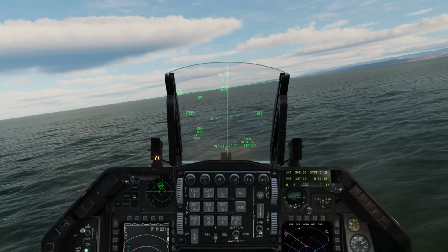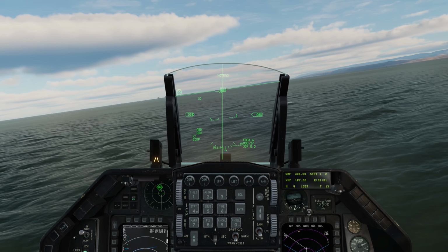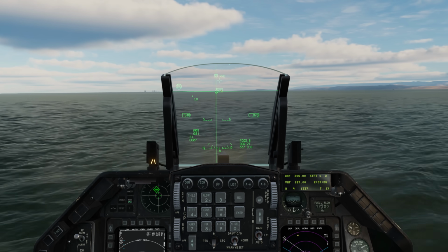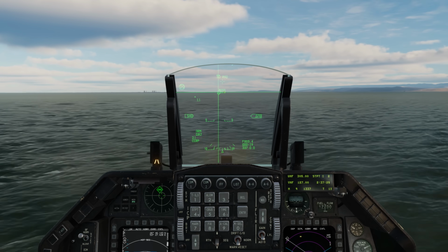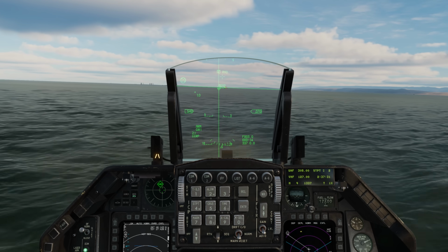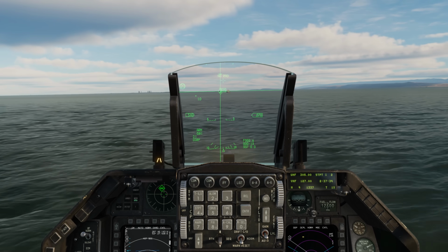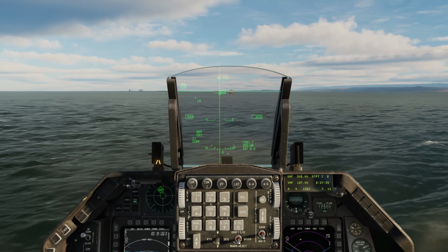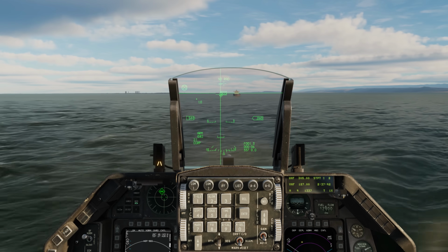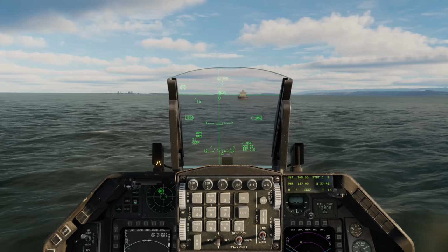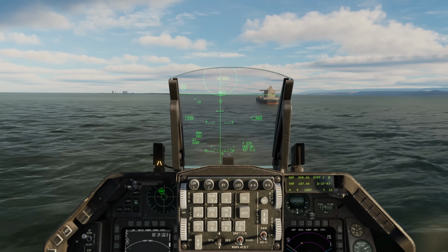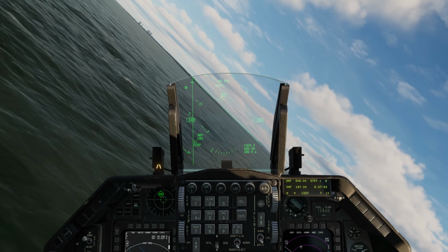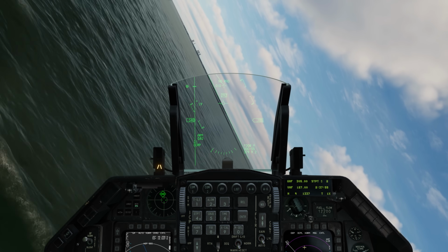I'm now going to set my HUD as my sensor of interest by going up on the display management switch. And right when I'm over this point, I'm going to press forward on the target management switch, or TMS switch, to set the overflight point. You have to do this. Okay, approaching IP. And IP. Okay, now I'm going to the target point as part of steer point 2.